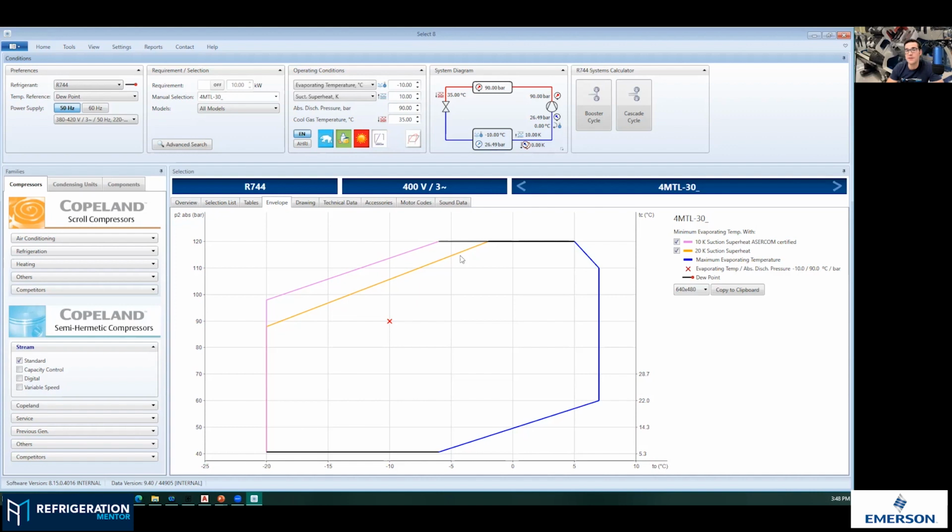But it's important to understand that when you're running that high compression ratio with lower mass flow, you're going to start to overheat. And that's really because you don't have that cooling coming back, like you said, right? Yes, exactly. So also the motor efficiency in that left area is lower. That's why there is even more waste heat coming from the motor, because it's running out of the typical operating point with the maximum efficiency, which is typically somewhere close to here.